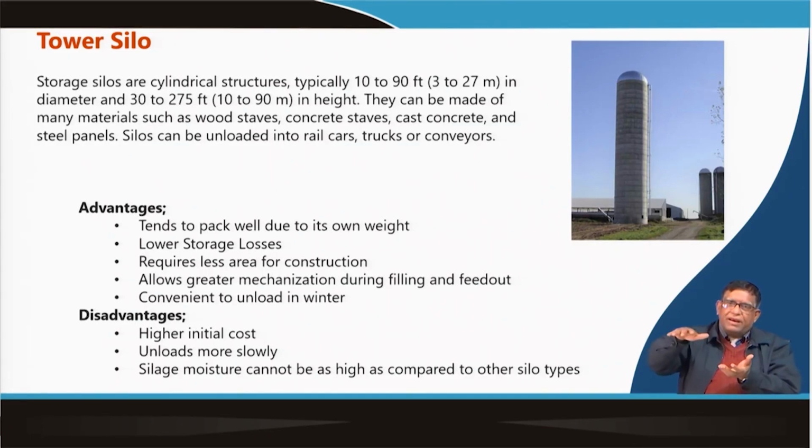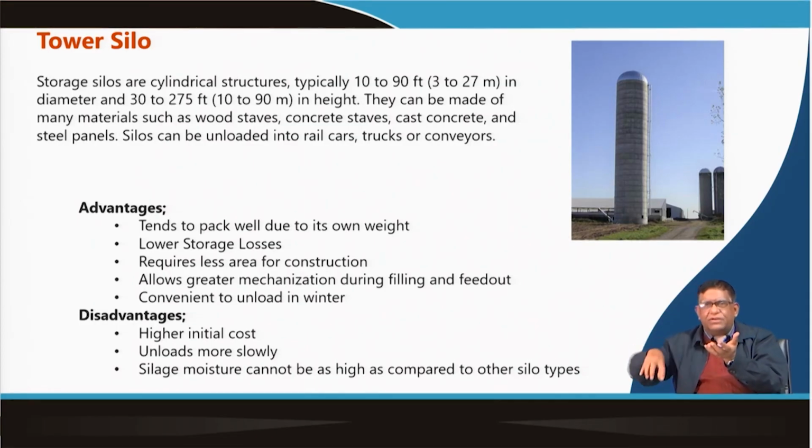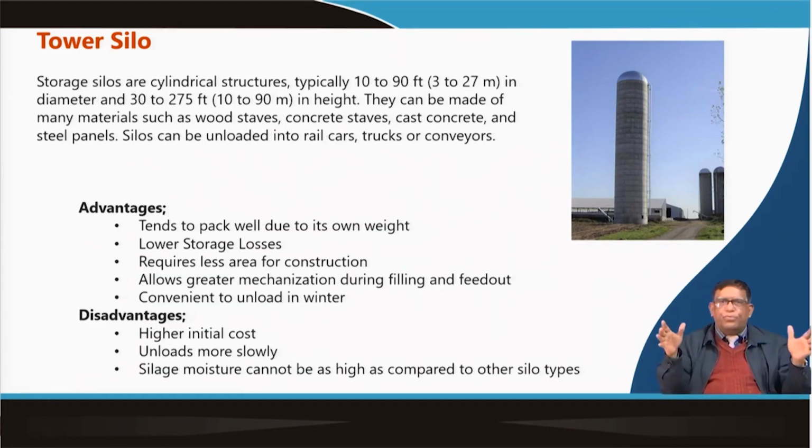The material will be dumped layer by layer, and the stacker will be climbing up the pile. And when it is to be evacuated, at the bottom there will be a screw conveyor, which will be taking the material out and giving it to the discharge point. So, there is no question of getting any arching or bridging or flow problem.